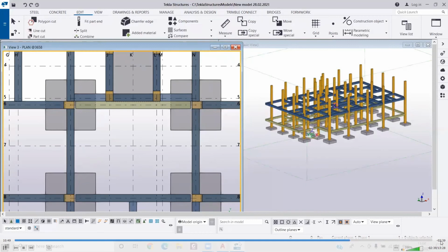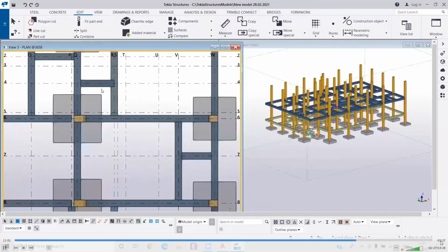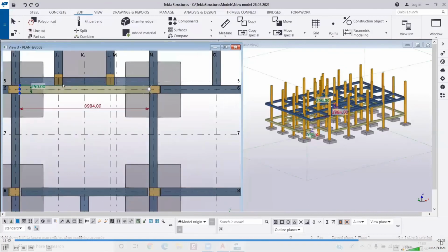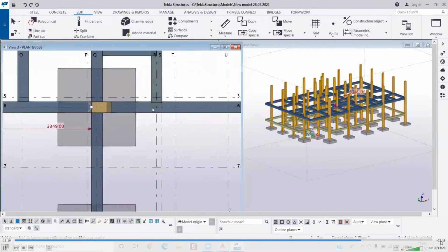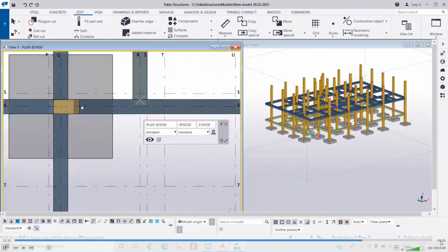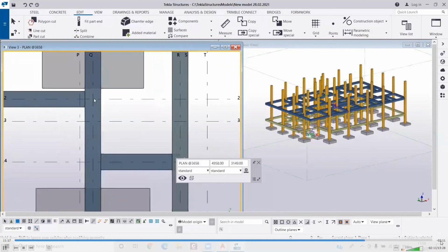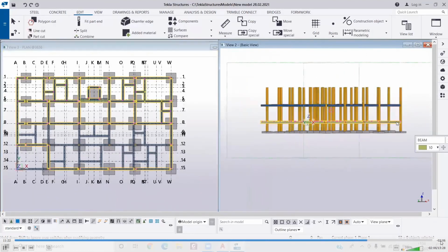So right now I am going to do all these things for this roof beam, but I will surely do it for the plinth beams as well. Okay, so you don't have to worry about that, and you can simply start shifting the beams over here. Okay, so I will just fix this plinth beam also, and whenever needed I can fix the plinth beams again. Okay, so that's not an issue. For now I will just stay with the roof beam, and once this modeling is complete I can go for the reinforcement.